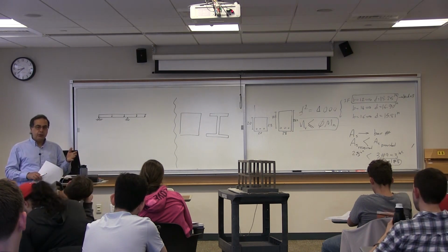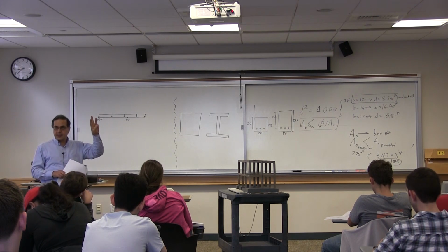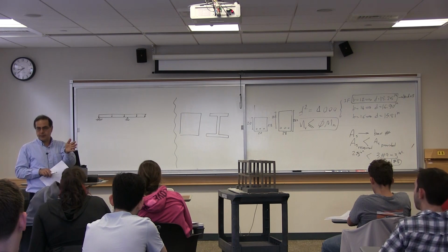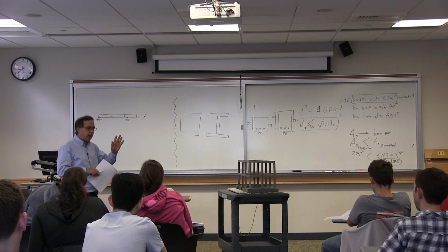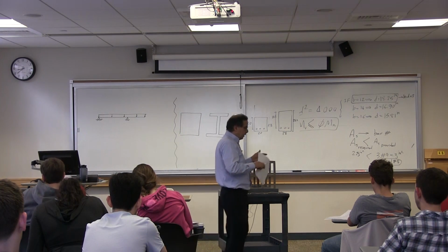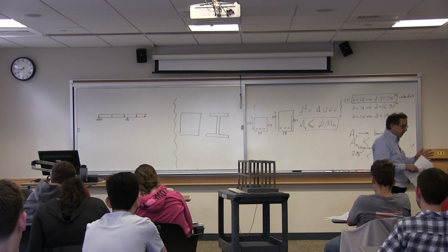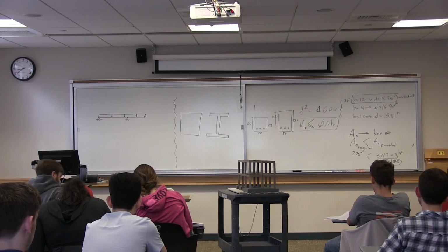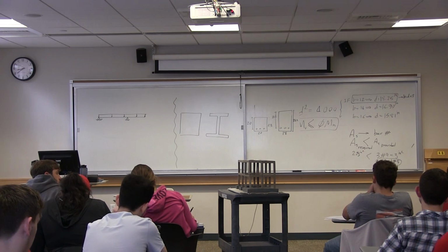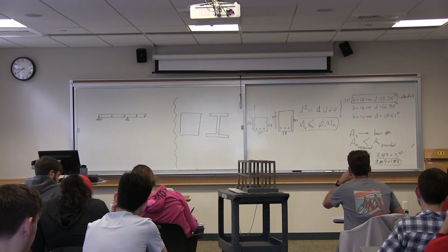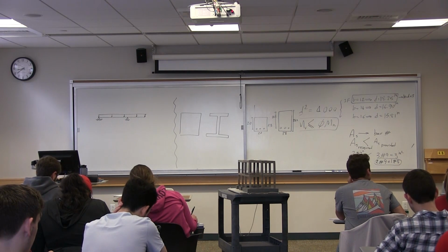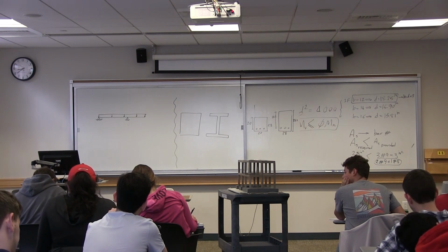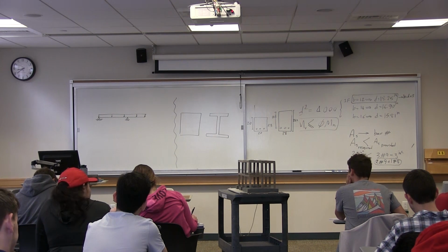In general, you design a beam for 3 sections: beam ends and close to midspan. That's in general, it doesn't hold all the time. In general, you design a beam at beam ends and the center line. In this case, you design for maximum positive moment and maximum negative moment. So let me first see how specifically the question reads here. Live load is placed. It explicitly tells you what to do.